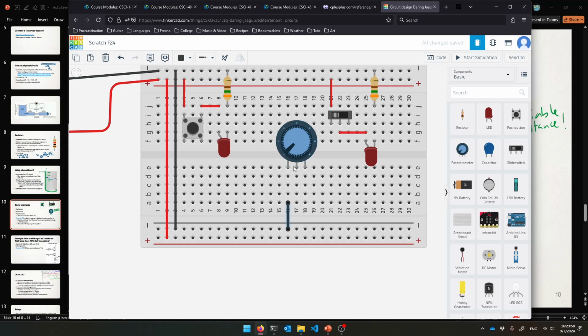So we'll do negative, and the more you turn it, the more resistance and the less current flows through. From here to here, you have less voltage as well. So we're hooking it into negative this time for fun. Then let's hook that into an LED. Negative needs to go to the cathode, so that's the right orientation this time.